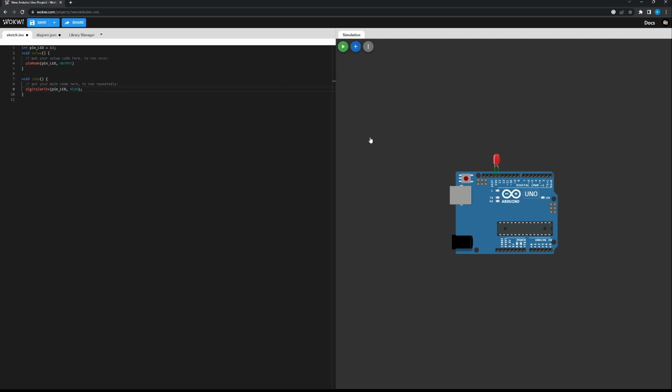For example, in the second lesson, we'll do a more comprehensive version of the LED toggling project. In there, we'll explain the functionalities and provide more background on the digitalWrite, digitalRead, and pinMode functions, and explain them in greater detail. So for now, just understand the characteristics of the setup and loop functions, and that's the main thing we're trying to show in the first lesson.